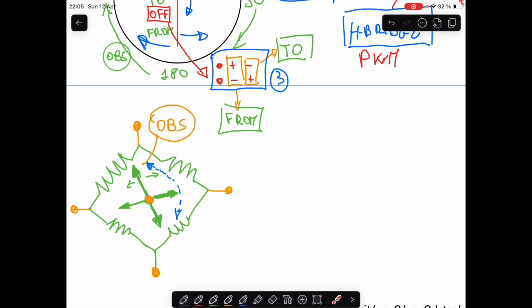The circuit was kind of like this: all these 4 resistors connected like this, and 4 outputs, plus a 5th output, which is in the middle. Once I started measuring things, I realized that these are actually rheostats. So when we turn the OBS knob, each of these resistors will display a different resistance according to the OBS position.